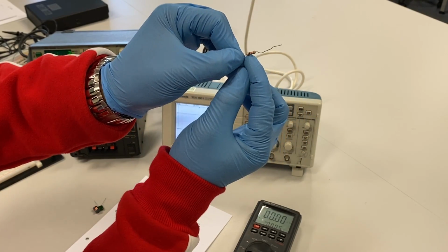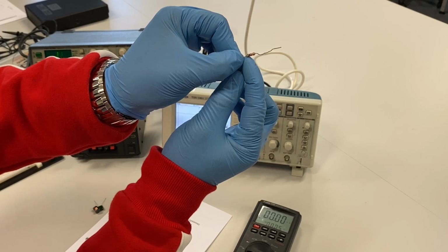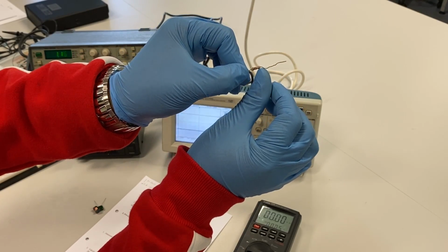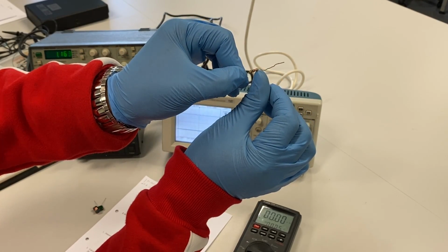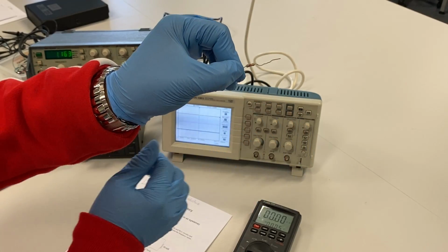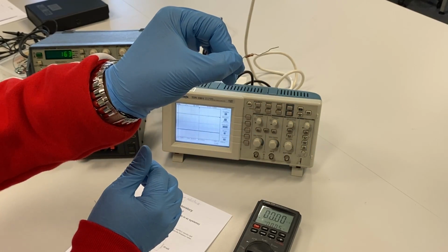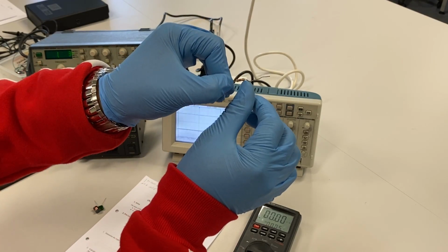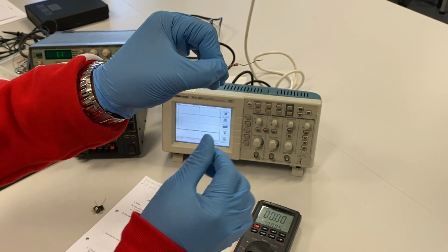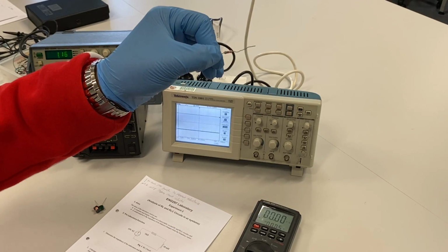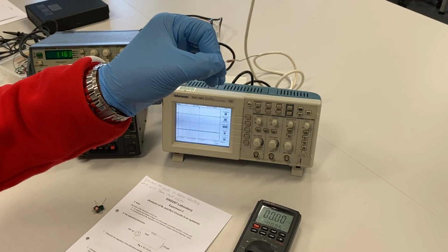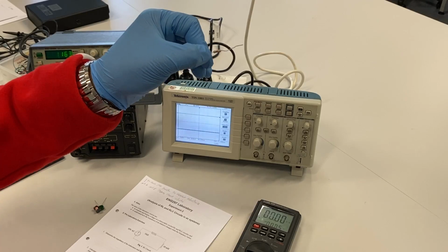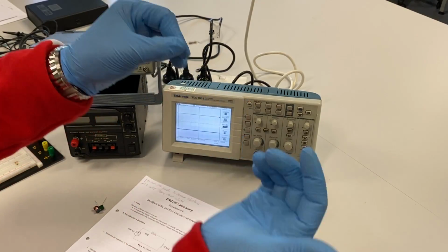So as I can see in those colors, what I said was brown, black, and red. These three colors represent the size of the resistor being 1K, and the fourth color at the other end, which is gold in this case, represents the resistivity. That means the deviation from the actual result. So if it's 5%, it means this resistor can measure maybe from 950 ohms to 1050 ohms, something like that. So that's what resistivity stands for.